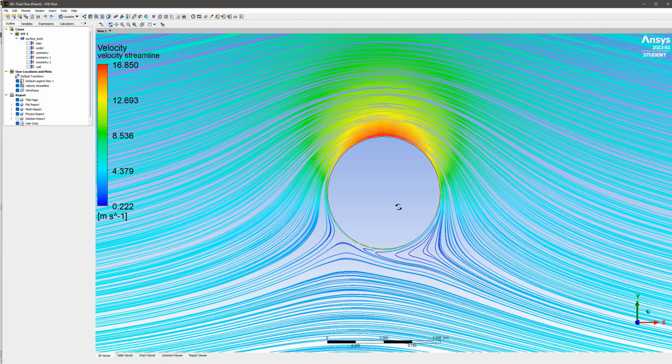This is because the cases in the project are based on the potential flow of an inviscid rotating cylinder, but Fluent can't actually simulate that because there's no drag. These cases are all theoretical, but when it is trying to simulate this, it does get close to having that stagnation point right there at the bottom.